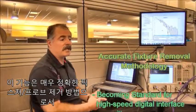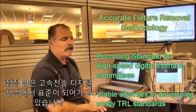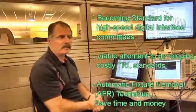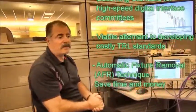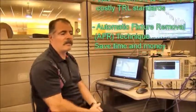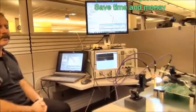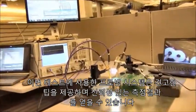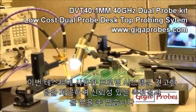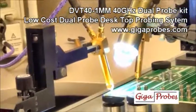It's becoming a standard in many of the high-speed digital interface committees. And so rather than struggling with through reflect line calibration kits, which require a lot of time and money, you can save a lot of time and money and use this newer automatic fixture removal technique. The probing system for this does not have to be extravagant or sensitive or fragile. You can have a very robust probing system that allows you to make a wide variety of measurements in high-speed digital applications.